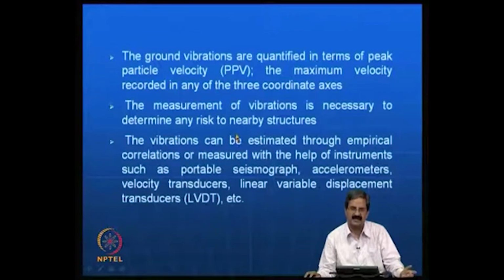So, how do you assess the effectiveness or the problem with these vibrations? This is assessed in terms of the peak particle velocity. In fact, the particles travel in the form of waves, and it has a certain velocity. You can use some pickups here and there and then pick up the velocity. What is the velocity of the particle that is traveling, right.